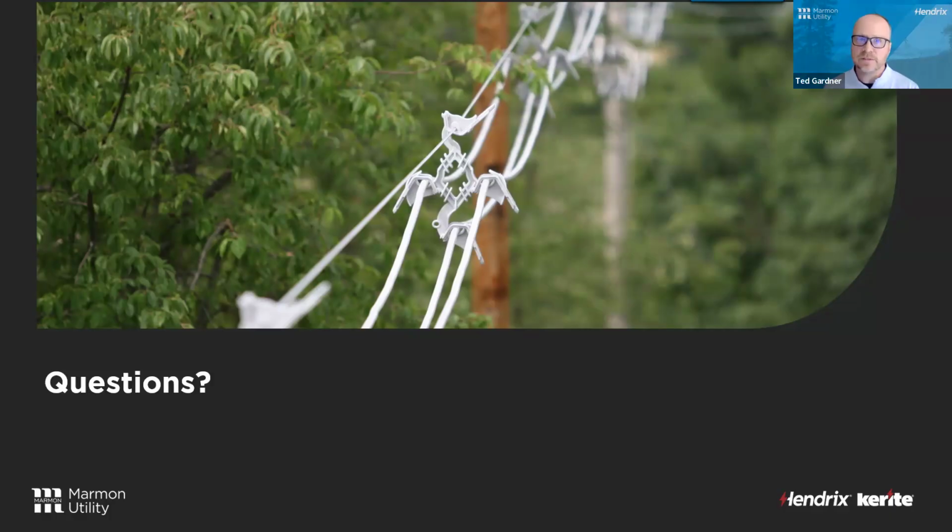So that's one of the reasons that you have to be cognizant of your span lengths when it comes to tree wire, and you don't really have that strong support of that messenger, kind of keeping it up in the air. So it is a bigger concern with tree wire than it is spacer cable.